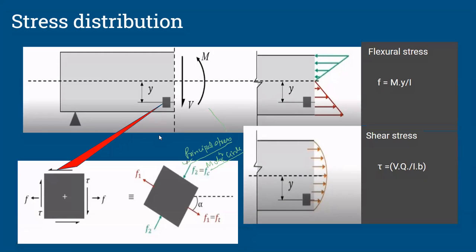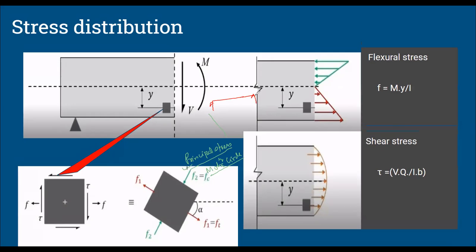तो इस situation में क्या होगा, just imagine it. इस situation में आपका shear stress भी रहेगा और forces भी रहेंगे. I mean, it will be bending stresses भी रहेंगे और shear stress भी रहेंगे. In simple, if I want to explain this thing, if there is a beam out here, अगर आपने कुछ load दिया है, तो definitely shear force कॉर्नर में maximum and it will be minimum out here, और bending moment कैसा बनेगा, I am drawing it, let me clear this up.